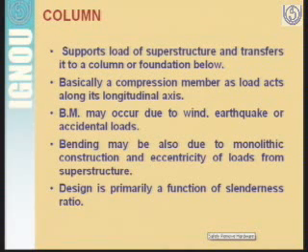Then bending moment may occur, or bending stresses may come in the section of the column. The reason for that bending may be wind forces, earthquake forces, or some accidental loads that may be in the lateral direction. Bending may also occur due to monolithic construction and eccentricity of loads from the superstructure. So this is also a reason for the bending.